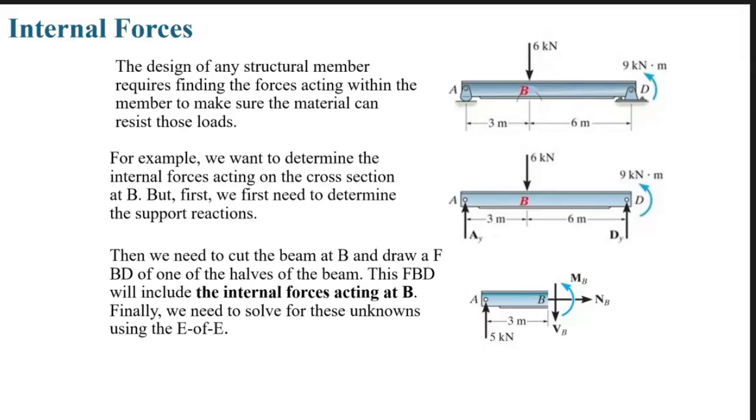Whether you are designing a bridge, a machine shaft or an aircraft spar, you always start with internal forces, then move to stresses and deflection analysis. When we analyze a beam, we want to find the force acting inside the beam, named the internal force, at a specific point. For example, suppose we want to find the internal force at section B.